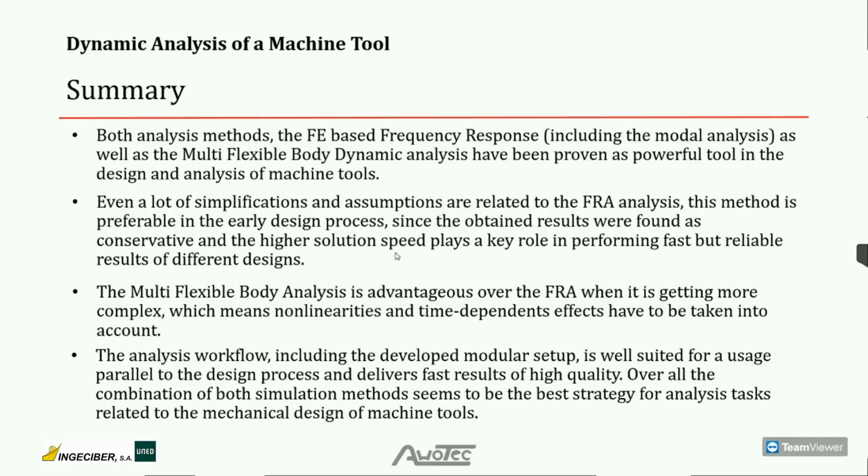Even though a lot of simplifications and assumptions are related to the frequency response analysis, this method is preferable in the early design process, since the obtained results were found as conservative, and the higher solution speed plays a key role in performing fast but reliable results of different designs.